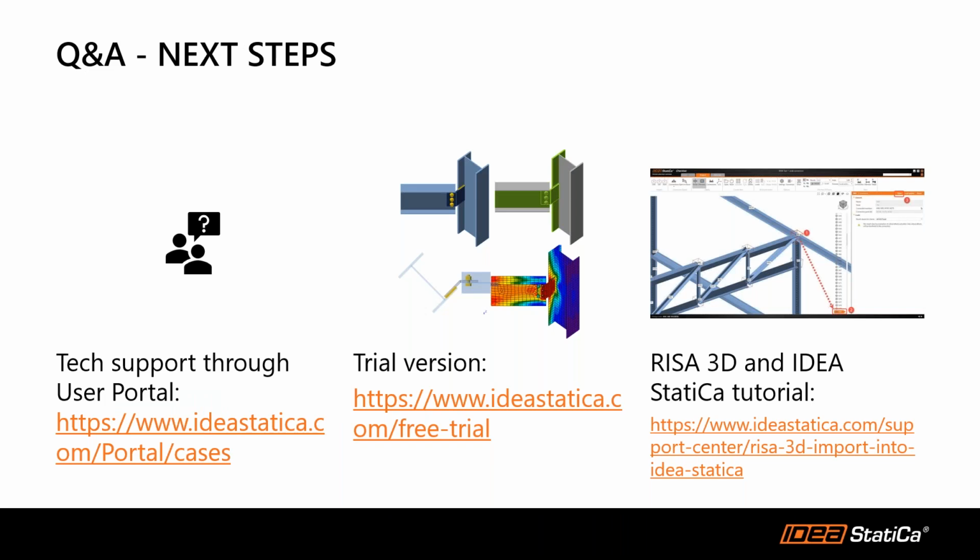A couple questions were coming through at the beginning, and feel free to send more questions as you have them. You can input them in on the panel. First question: does the default RISA local member access convention also need to be changed? I think this has to do with when you were modifying the vertical global axis. So they're asking if they also need to change the local member axis. Okay, no, the local one does not have to be changed in the RISA application.